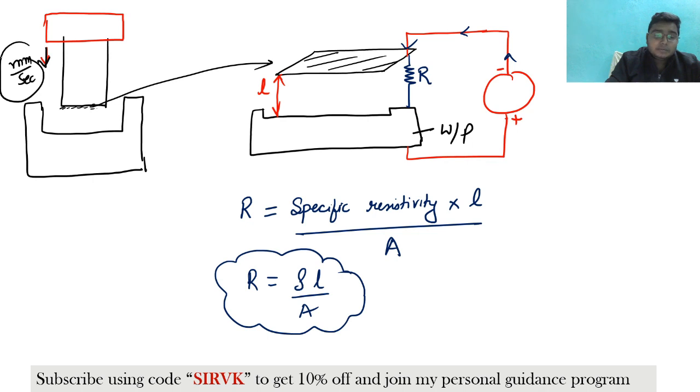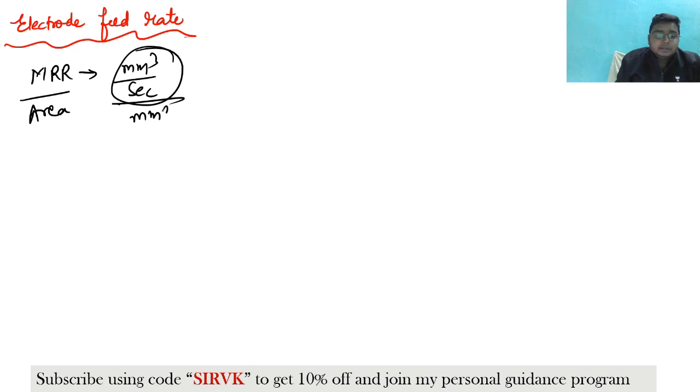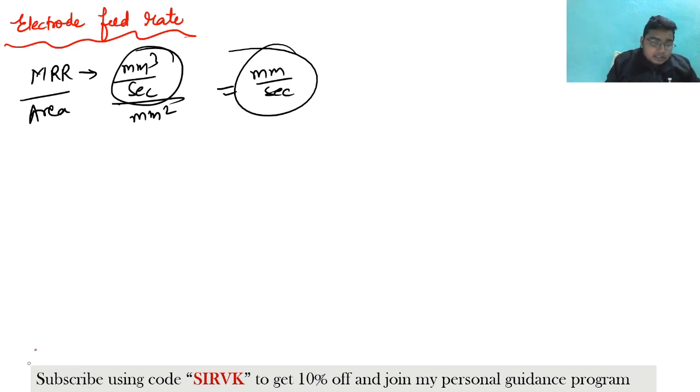So if you can understand from here, the unit of MRR is mm cube per second. If I divide this MRR by area, then what will be the unit here? The unit will be mm per second, isn't it? Because mm cube and mm square will get cancelled out, and hence mm per second will be there. So what I am going to write here: the electrode feed rate will be MRR divided by A, where MRR is EI by F rho. Clear? Divided by A.